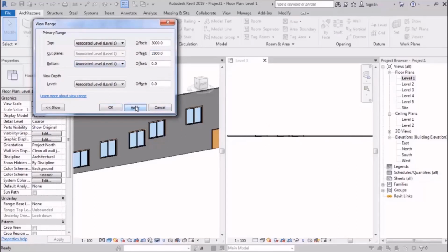Now apply. Well, two things happen here. One, one of the windows disappeared. Two, the doors disappeared. Let me undo so that you can see when it was 1.80, we had the window here and two doors there. But when I change it, you see what happens? Well, this one appeared, but one of our windows is gone and also two doors.